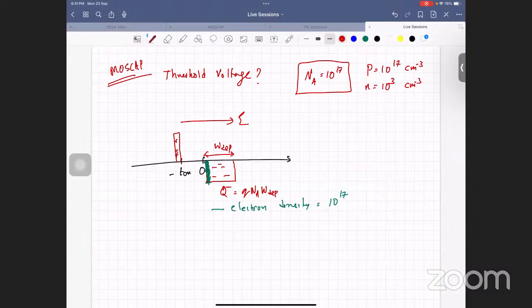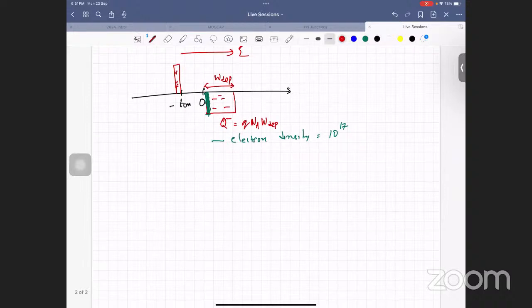Threshold voltage is not only for inversion regions. You can also define a threshold voltage for a diode where there is no inversion. In a MOS capacitor, it is the threshold voltage for inversion. But if you have a PN junction, when you draw the I-V of a PN junction, there is a linear region, you extrapolate it and say that there is a VT, above which the current significantly increases. This is a threshold voltage in the context of a diode.